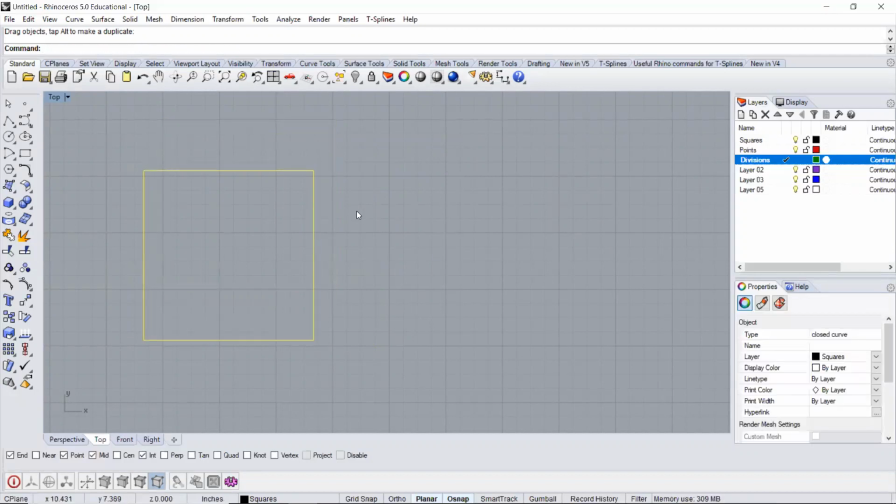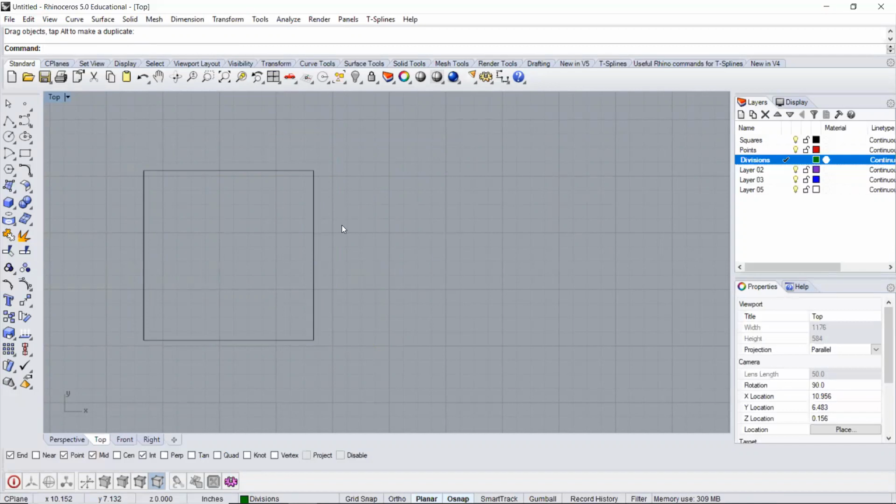The other more precise way to move them would be similar to our copy command that we talked about in video number 2 or 3. In order to use the more precise movements, we'll use the move command. So that's M-O-V-E, and then follow it up by hitting return or enter. And if I come down here to my toolkit, I talked about where the option was for copying using the toolkit icon. There's also one for moving, and then we'll get to the rotate 2D one as well.